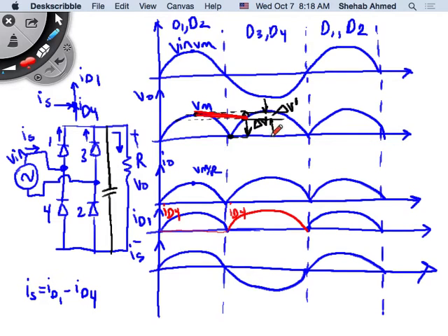Right. So now, how is the circuit operating? If I put this capacitor in there, initially what's happening? The capacitor is not charged, correct? For example, assuming the capacitor is not charged initially, then the capacitor voltage. I'm drawing the capacitor voltage or the output voltage because they're the same, right? The capacitor voltage and the output voltage are parallel, right? So initially the capacitor voltage is 0, so the output voltage is 0.